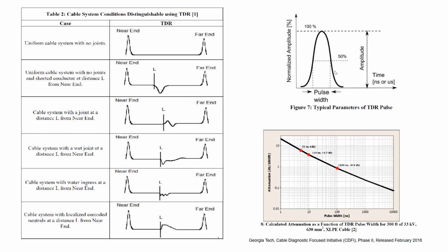Normally it is a bell-shaped curve actually, not a pure rectangular pulse. So here you can see the pulse width is measured at 50% of the height. Because it is bell-shaped, we have to decide at which place we measure the width of the pulse. So it is normal practice to measure the pulse width at 50% of the height. This is 100% of the height, and at 50% of the height, what is the pulse? That we call the pulse width.